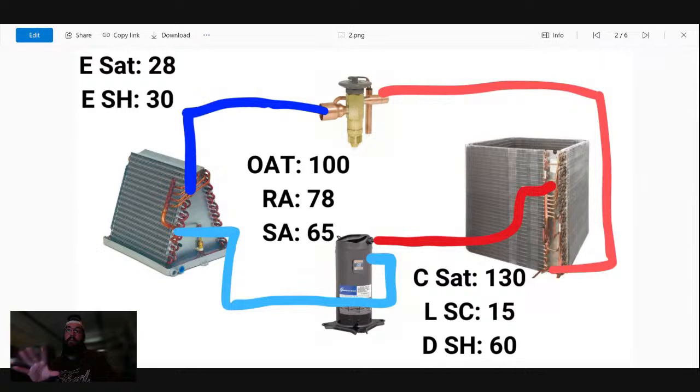Now at this point, you're going to give the whole system roughly at least 15, 20 minutes. I also recommend as much as possibly 30. Really, if you wanted a more scientific way of knowing when is a good time, one great thing about the Bluetooth probes, I know for sure Testo, and I'm pretty confident Fieldpiece has this as well, you can graph the readings.